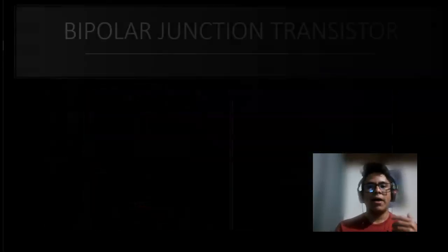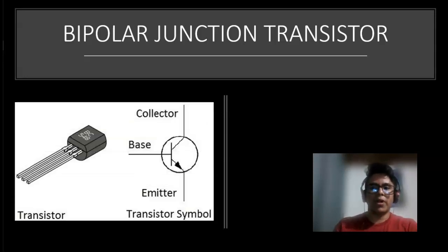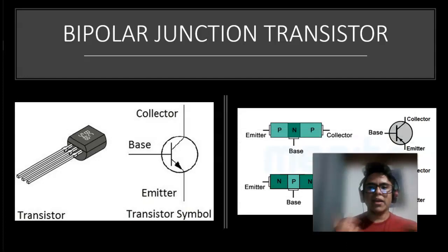Secondly, we have the BJT, or better known as the bipolar junction transistor. They are basically manufactured in a single crystal of germanium, silicon, or gallium arsenide. In the crystal substrate, regions are contaminated in a very controlled way, two of which are at the same time NPN or PNP, forming two PN junctions. Such contamination, or doping, consists of adding impurities to the material or element, making it conductive as required.